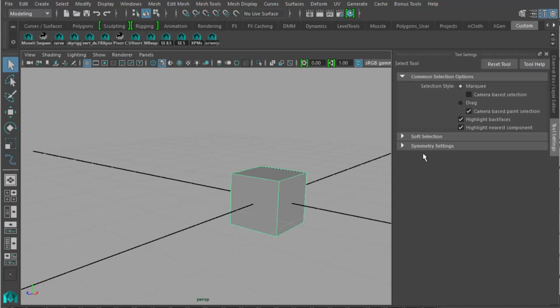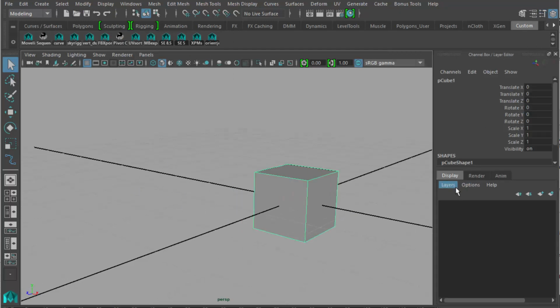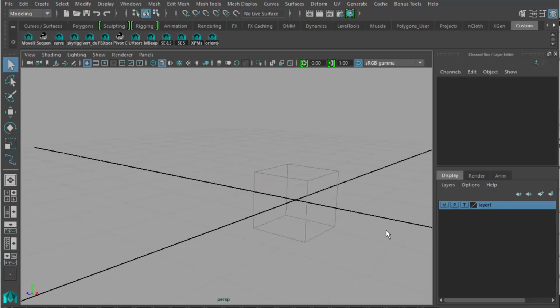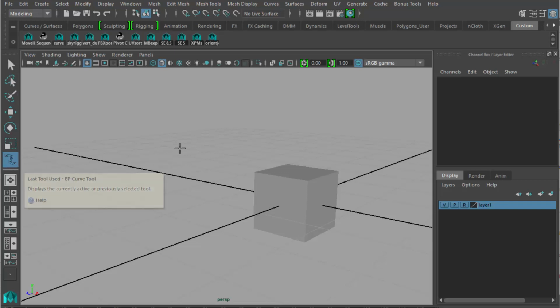And using this, I prefer to bring it into a layer. By virtue of turning it not into a template, but clicking on this and turning it into a reference, you can go back into your curve tool, which, by the way, whenever you use a tool, it should show the icon here in Maya on the leftmost bottom of the controls, or you can press Y and it will take you back to the last tool used.